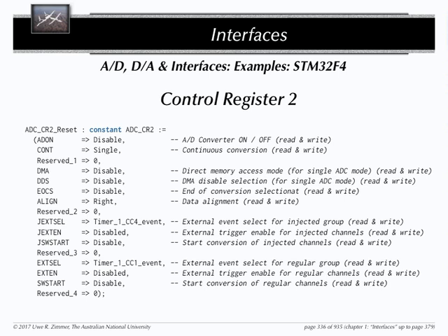Okay. Now, this is driver level 0 here. This is the driver level which directly hacks into the registers of my device level. Now, what you provide on the next level up is usually some function-oriented, procedure-oriented interface, which gives you, for example, an interface which says, give me a single 8-bit converted value between these two channels.